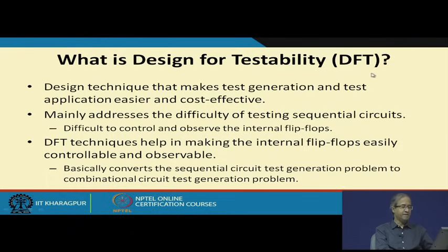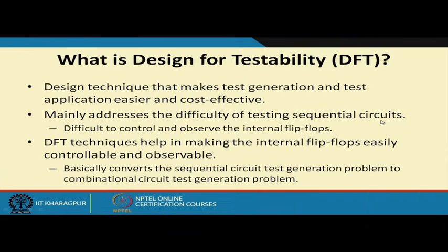Specifically, the DFT techniques that are used in practice address the difficulty of sequential circuit testing. You see, I mentioned that for sequential circuits, the main hurdle are the flip flops. They are sitting inside that black box which is the circuit, and I can apply inputs only from outside. So, unless I initialize the flip flops, I cannot run a test. This is a major problem of sequential circuits.